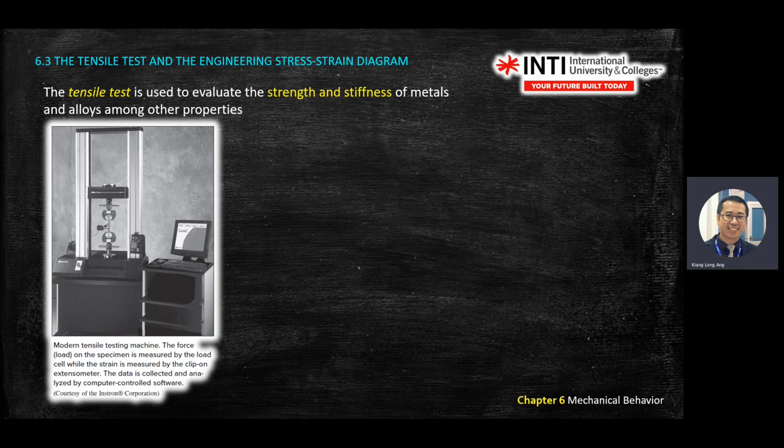When you pull, there is a sensor to sense the elongation. It still goes back to the definition: when you pull, it can calculate the strain. There's also a sensor for load, which senses the force. And in the computer program, you can enter the original cross-section area. This data is collected at up to 0.01 second intervals, or even higher, because we are now in a very advanced era. Our computing power is very good, so you can get very sensitive data.